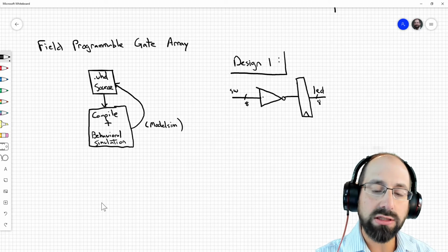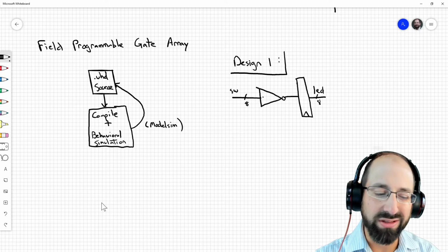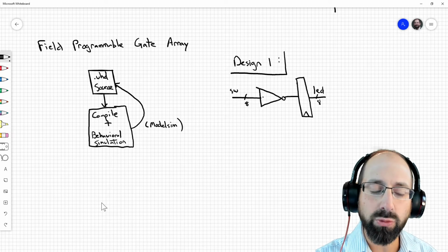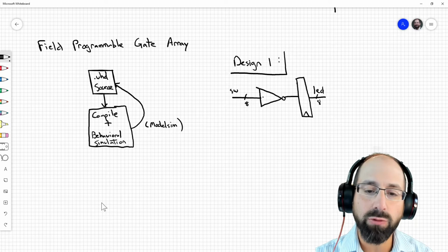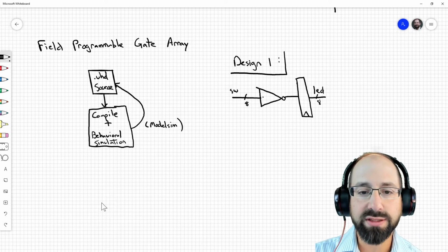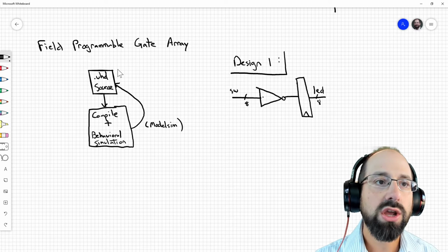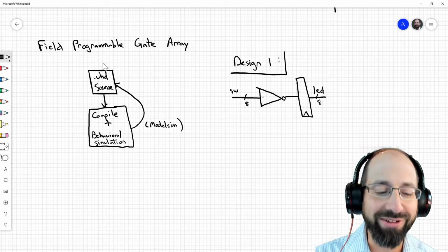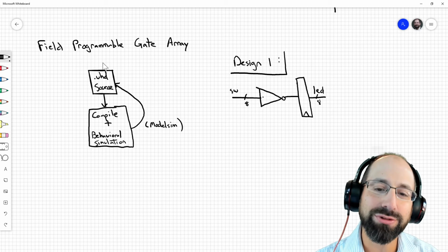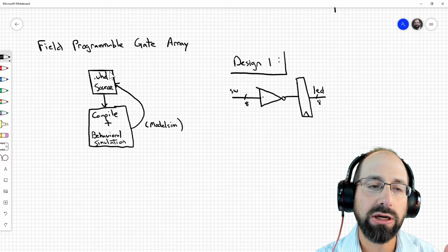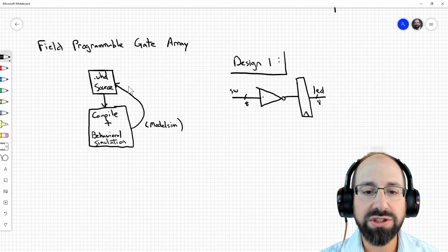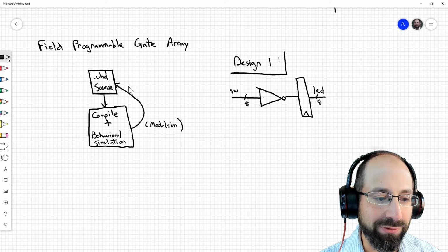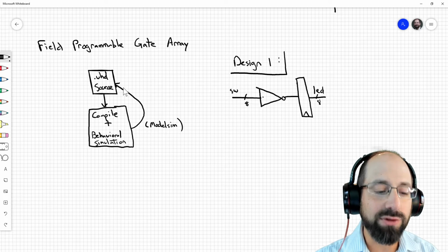And what we also started to talk about last Friday is a very little bit about field programmable gate arrays. I don't know how much in the weeds I'll get in that today. I care more about the tool flow than about the device itself for our purposes. But the tool flow is significantly different than what you've been doing so far. It starts off very similar. What I'm attempting to depict here is, technically you start with your diagram, your schematic, your idea, but then you're entering things in terms of your VHDL source or your Verilog source, and there's this loop that you've gotten pretty familiar with so far, which is you save your file, you compile your file, you execute some sort of behavioral simulation.